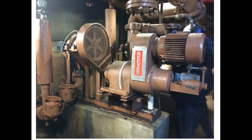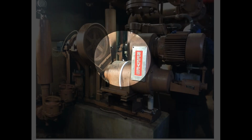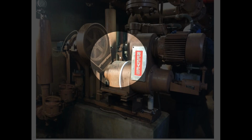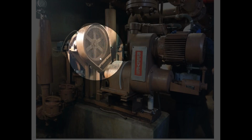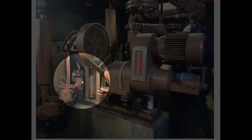A couple examples of aging equipment that's out in the market are still these plunger style pumps. This is one example where you see a lot of ancillary equipment around this pump. You've got pulsation dampeners, you've got extra valves, you've got sludge that's now open to the atmosphere every time there's pulsing, and you can only work on one side of this pump.